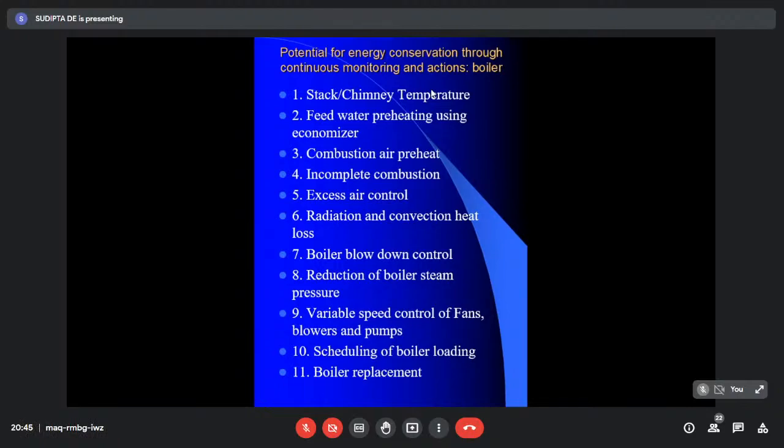Okay, the excess air you are giving, why are you giving it? Because the stoichiometric air fuel ratio would not reach, make complete combustion. So your unburned fuel will be there. It will be an incomplete combustion. So you are bound to provide some excess air, because this is the difference between pure science and applied science. Though pure science has perfectly told that the stoichiometric air fuel ratio should be enough for the combustion of that particular fuel, 1 kg of fuel, and accordingly how much air will be required. This is stoichiometric calculation, and that's absolutely perfect. If you can make proper mixing of the air and fuel, every fuel gets the air or oxygen content. But that will never happen in a real life system. So some excess air has to be there.